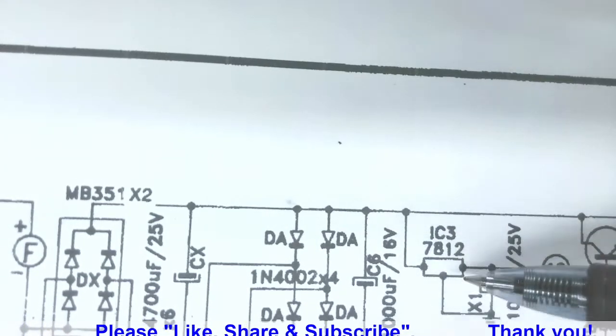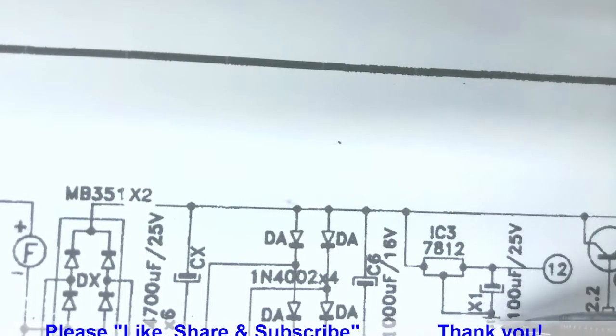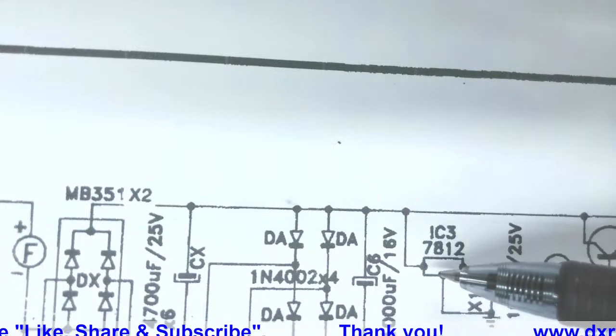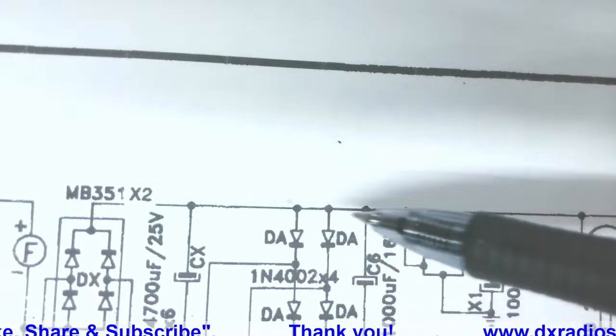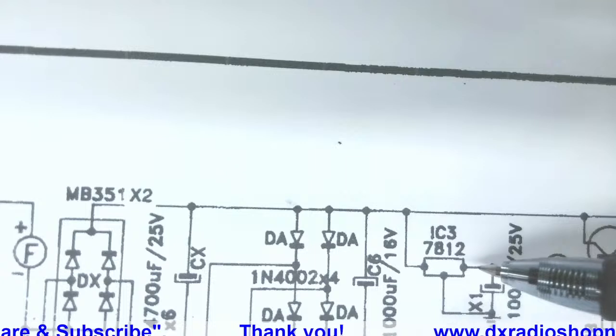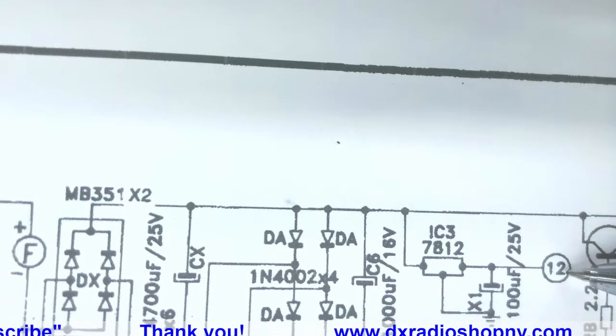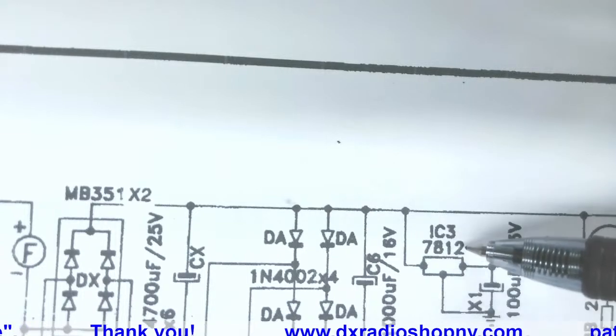How they got like a little box formation? Here's your ground symbol. IC3 7812. Well, that's going to be your voltage in, probably 18 to 20 volts coming across here. Ground out to this point. That's going to be your 12 volts. Right here's 12 volts, because that's what this regulator is.